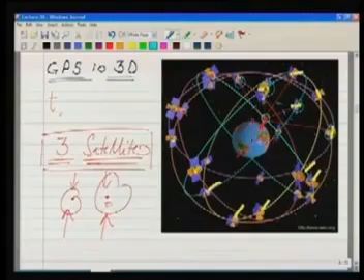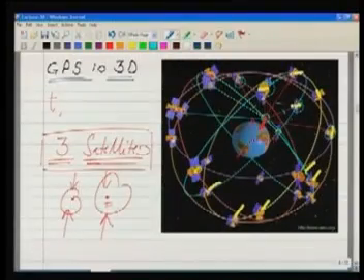but we would like to go for more number of satellites, because we know redundancy is always desirable. If, for example, as in this figure, we are able to see more number of satellites, so what we will do, we will take all these satellites into account, we will measure the distance from receiver to all these satellites, and then we will put all this together in order to find the best possible solution, which is coming by the least square, as we saw also in the case of adjustment.